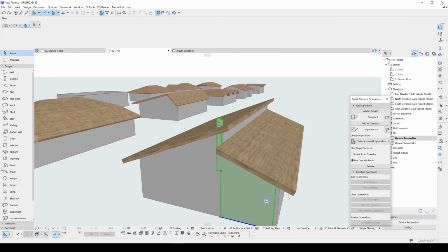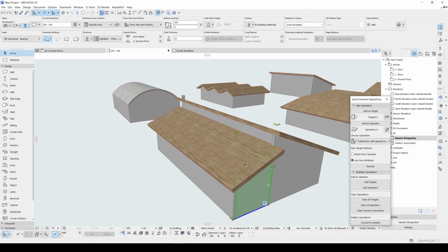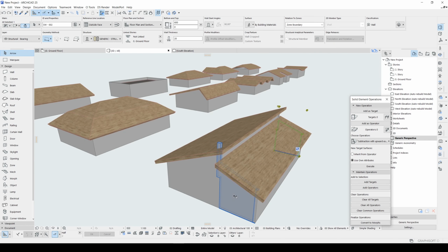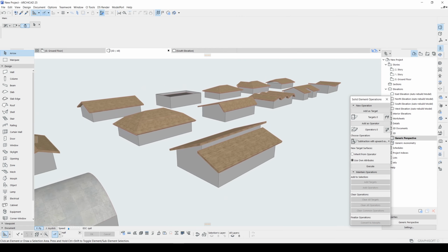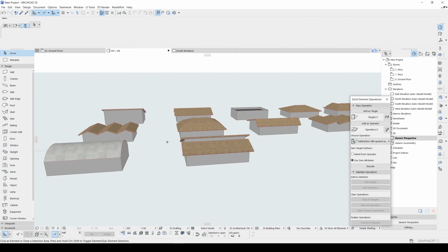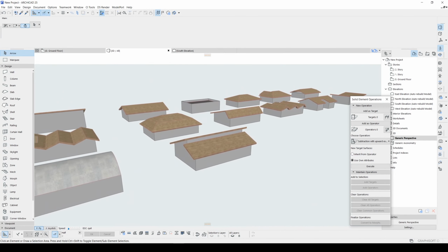Again, if you see errors like this, the solution passes from clicking your problematic walls, and from the settings you can decrease the junction order. Now they will be fixed. I think this was the hardest according to all of them.